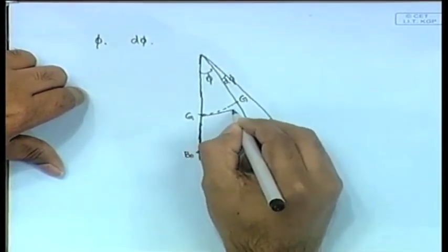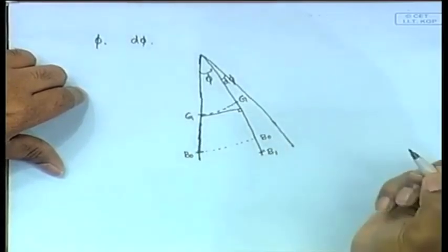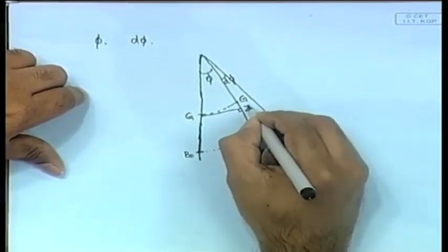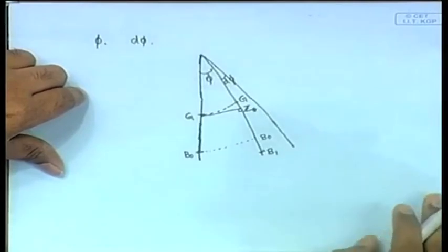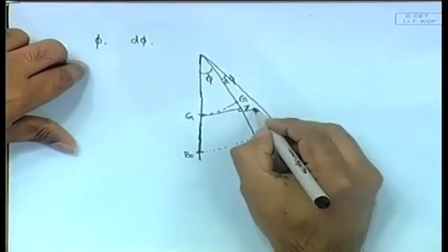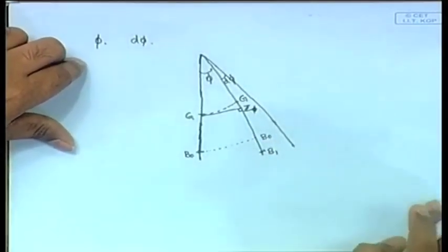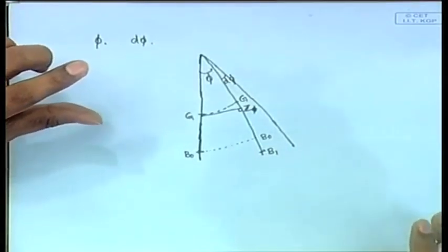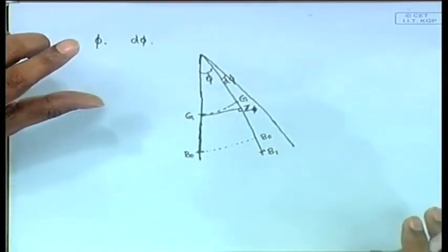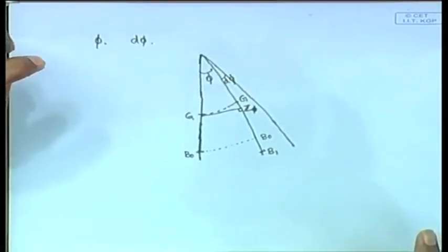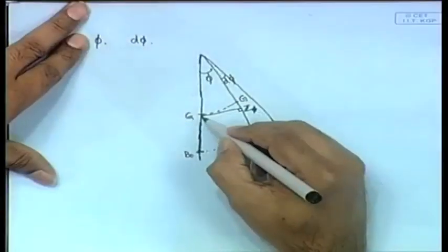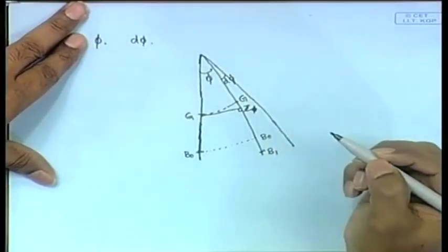Let us suppose this is the vertical, this is 90 degrees. So I call it GZ phi, not theta. GZ phi means it is the GZ when the angle of heeling is phi. Is that figure till now clear? I will complete it and maybe explain further. So this is GZ phi.